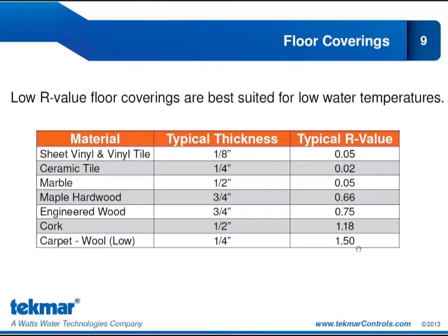So if we want to stay as low as possible, we're looking at the vinyl, ceramic, marble. Those make excellent floor coverings for radiant installations. And then the further down we go on this list, the more insulative that floor covering is going to be, which is obviously not ideal for a radiant operation.